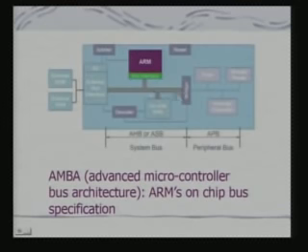On the main bus itself, you have an on-chip RAM, because that will be fast enough. The external bus interface block is also connected to that same bus, and there is a bridge. Through the bridge it can be connected to a peripheral bus, because the peripheral bus can possibly be slower compared to the system bus. So it is a kind of hierarchical bus organization.